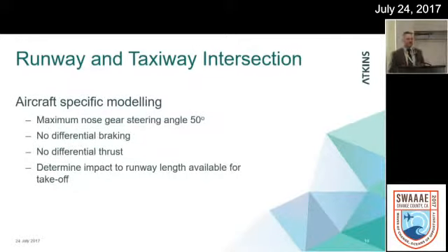So when we do aircraft-specific modeling, the Advisory Circular 13A has very specific criteria that are used. We cannot have a maximum nose gear steering angle of greater than 50 degrees. We don't want to overstress the nose gear of the aircraft making the turn. We don't want differential braking, and we don't want differential thrust. Honestly, we did do a model that locked up the left differential braking. We did full thrust on one side, reverse thrust on the other, just to see what the aircraft would do. But we didn't share that because it was a little bit aggressive. And finally, the goal here is to minimize the impact of the runway for takeoff.